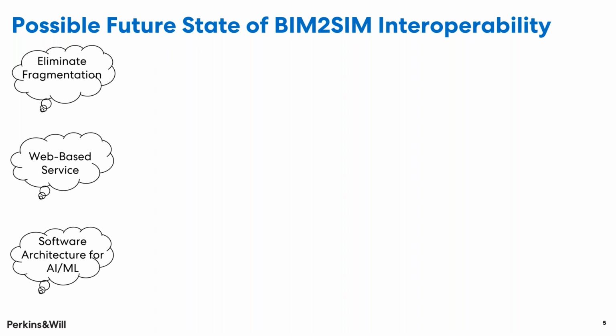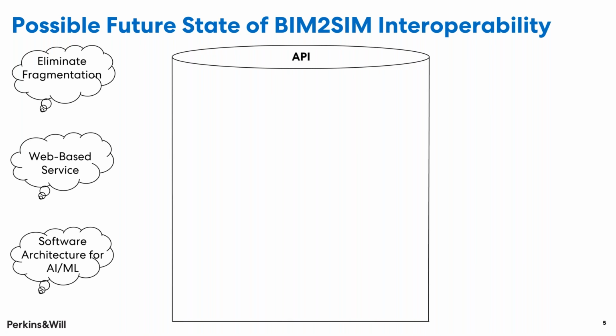Now, ignore the political and IP issues. I know they're significant, but there is precedence here for a system like this. Imagine this is up on the cloud and you have an API, and the user uploads their native BIM model. The reason we want the native BIM model, Revit, Rhino, what have you, is that, like Jim said, when you look at that gbXML file and you're trying to figure out how to fix it, or if that represents the actual geometry. Without that contextual native geometry, you don't know exactly how to self-heal it or if that is representative.